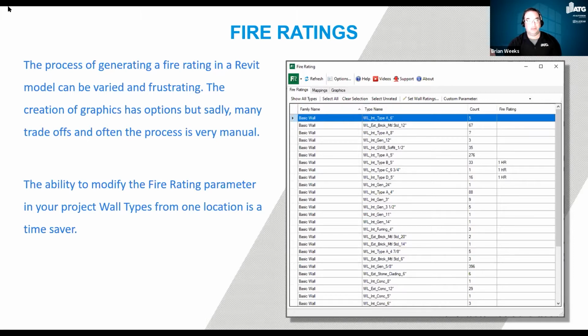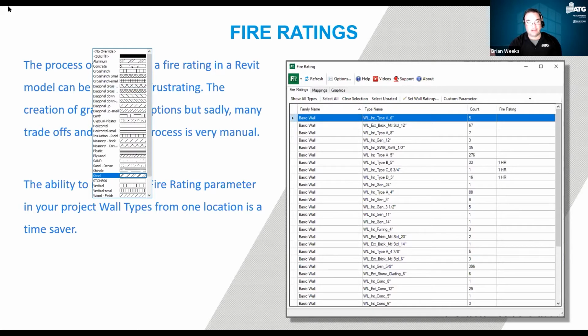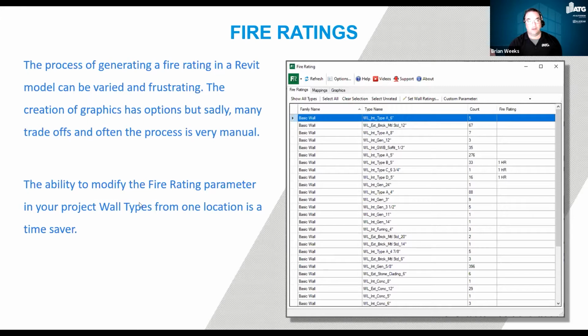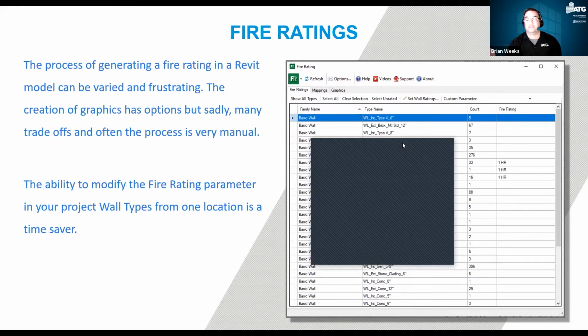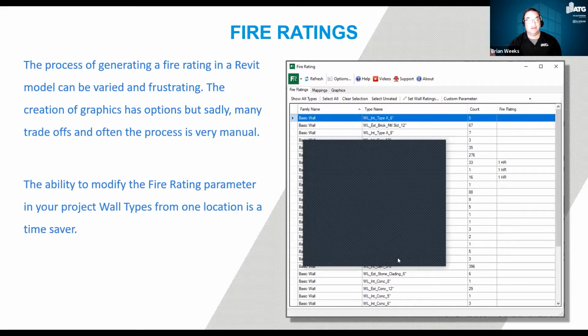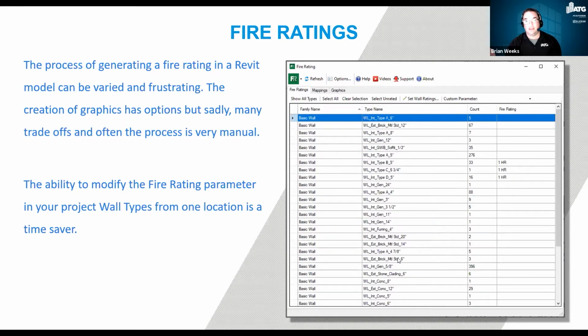If I apply a filter to this view, we already have this rule-based filter set up that talks about the 1 hour rating. And if I want to apply a pattern to that, through Revit as an out-of-the-box control, that's something we can apply and get that to show up in my view as a 1 hour, or if I need to also apply the 2 hour.